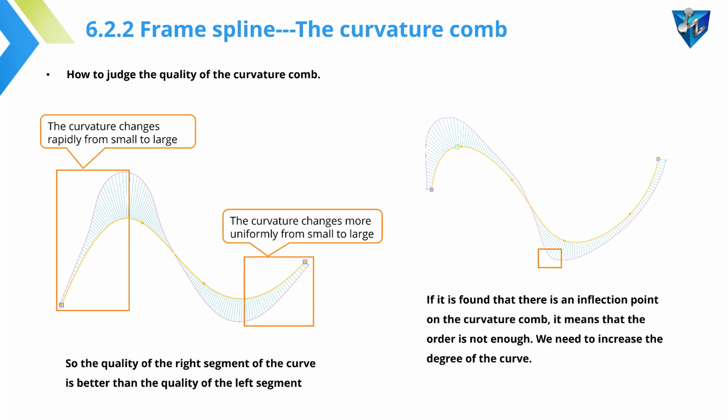We can adjust the spline according to this method in our daily design. If you find an inflection point on the curvature comb, it means the order is not enough. We need to increase the degree of the curve.